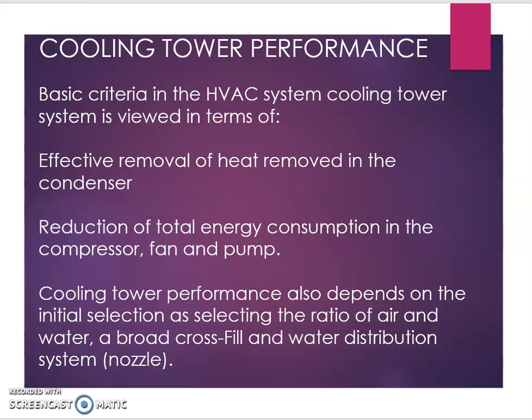So next one is the cooling tower performance. The cooling tower performance can be evaluated based on several criteria, which is the effectiveness of removal of heat from the condenser. And then we have the reduction of energy consumption in the compressor, fan and pump. This is related to heat removed from the condenser. And then the cooling tower performance also depends on the selection of the ratio of air and water by the crossflow and water distribution system, the nozzle inside the cooling tower.